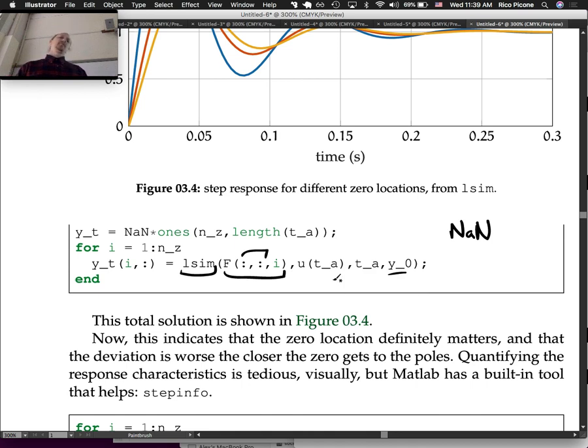And then another thing to note is you don't have to give it a time array either. In fact, it ignores your time array for the actual simulation, but it just returns the simulation values at your time array points. So if you don't give it a time array, it'll actually return a time array that it calculated for you. I don't like that very much. It's not really my style. I like to roll my own, right? So I don't want MATLAB making this array for me. I don't know what size that array is going to be when it comes out. It makes me uncomfortable.